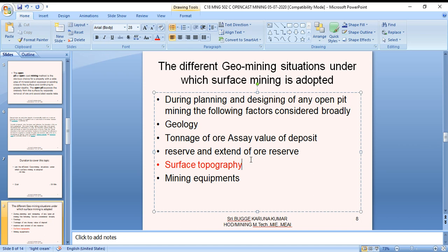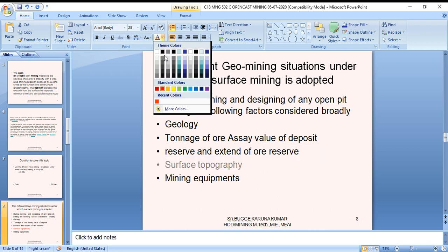Most of the iron ore mines are in hilly areas. For example, Kudremukh Iron Ore Company Limited extracts the ore, and it is transported by gravity itself. That is one advantage. Similarly, in some Godavarikhani areas, the open cast is near the Godavari River. An important bund is required for any tank there, because if flooding happens, it will merge into the water. So surface topography is very important. Generally, by level instruments you measure all the survey points and various leveling points. This is called the contour map you maintain. According to these contours our methodology will be decided, so this is an important factor while adopting the method.